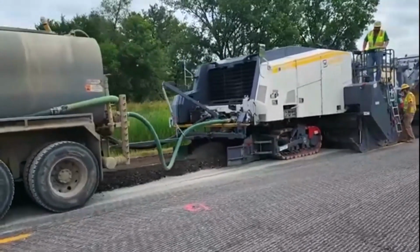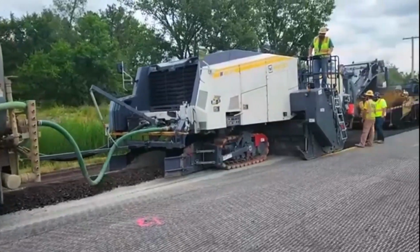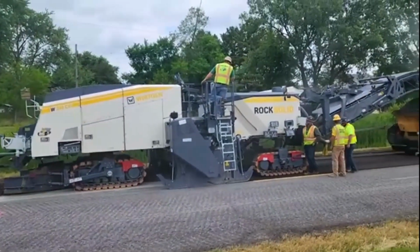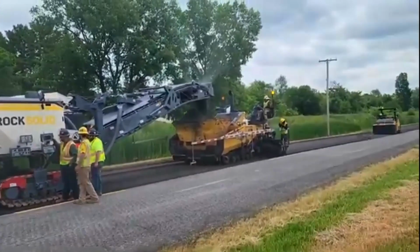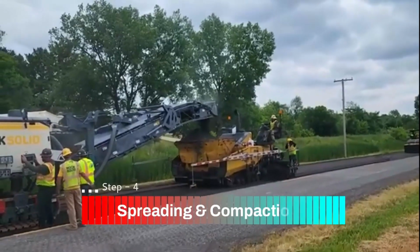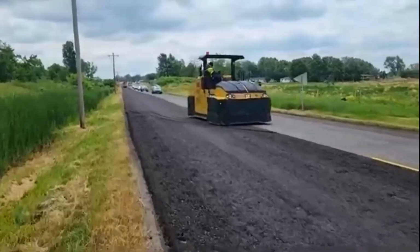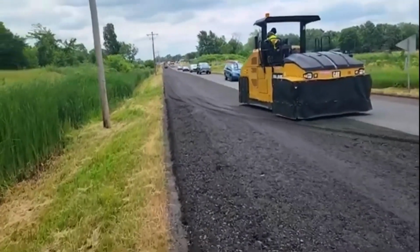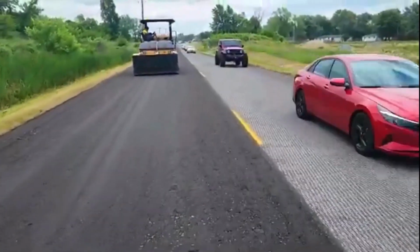If bitumen emulsion is used, bitumen is sprayed evenly across the material. Additional water is added for moisture control. If cement stabilization is used, cement, typically 2 to 4%, is mixed with water to improve strength. Step 4. Spreading and compaction. A grader spreads the stabilized material evenly. A vibratory roller performs initial compaction. A pneumatic tire roller provides final compaction, ensuring a durable surface.